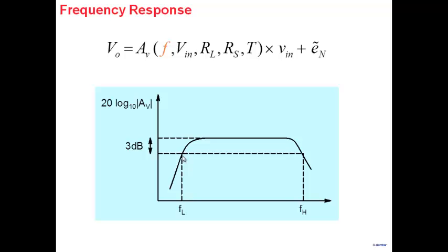So it's telling you the lower frequency range up to which maybe you can use your amplifier. Don't go lower than FL. Then you are in trouble because gain is a function of frequency. Also, it tells us don't go over FH. Gain again becomes a function of frequency and starts dropping here. So besides the mid-frequency gain, what are the two other important parameters that we know of an amplifier now? FL and FH. Sometimes people take FH minus FL and they call it the bandwidth